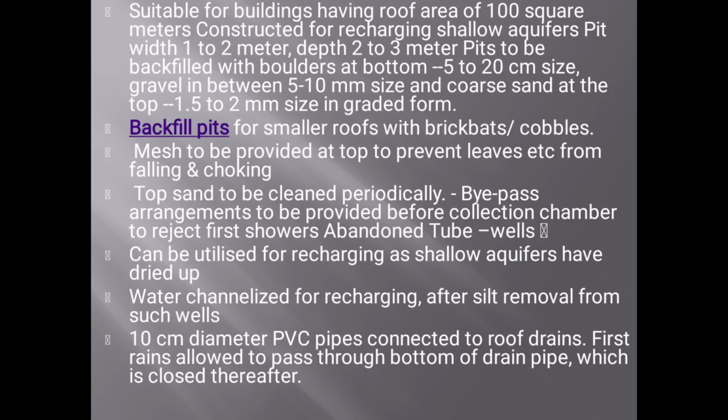Suitable for buildings having a roof area of 100 square meters. Constructed for recharging the shallow aquifer: a pit backfilled with boulders at the bottom of 5 to 20 centimeter size, gravel in between of 5 to 10 mm size, and coarse sand at top of 1.5 to 2 mm size in graded form. Next one, backfill pits for smaller roofs with brickbats and cobbles, with mesh provided at top to prevent leaves etc. from falling and choking. Top sand to be cleaned periodically.